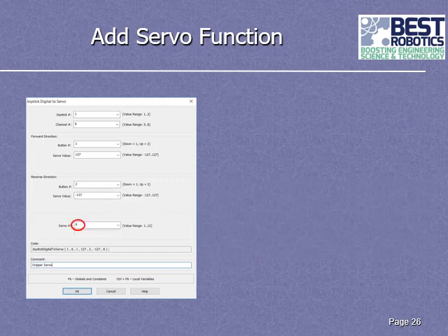Again, you have to pick a motor port, so just pick one that you haven't used before. One good rule of thumb is you have basically ports 2, 3, 4, 5, and 6, and 7, 8, 9, so you have like 8 ports you can use. Try to spread them out amongst the first 4 and the second 4. It's kind of a power management thing. I'm not going to go into the details of that, but if you can, especially with the bigger items like the motors, keep them on different sets of 4 just for power management. So in this case we're picking port 8.